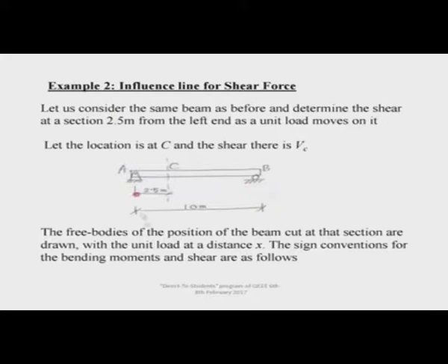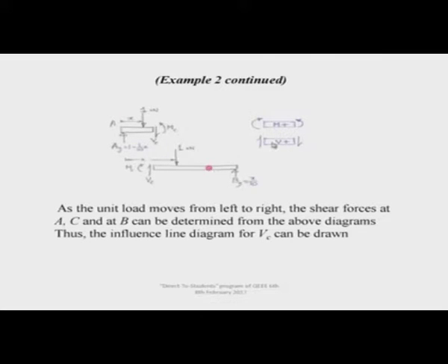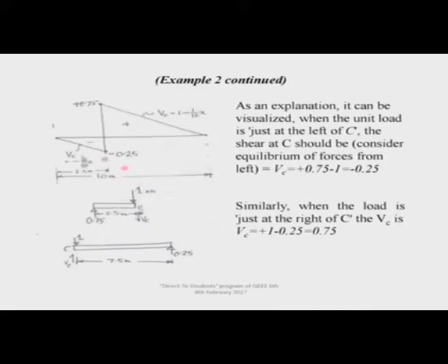Now, see the shear forces. I need not explain in much detail, because we just need to know statics. I need to draw the free body diagram at a section. If the question is how the shear force changes when a unit load moves onto the structure, I can have the unit load here, take a section for different parts of the free bodies, solve the static problem with my sign conventions, and find the shear forces as the unit load moves, and we will land up with this kind of diagram.